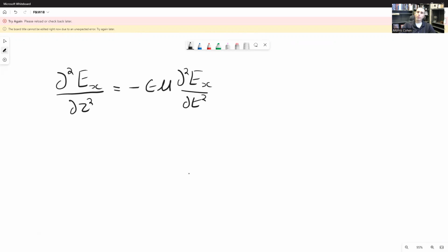All right, now, one thing that we had figured out earlier when we talked about phasors was that taking a time derivative, if we convert that into the phasor domain, is equivalent to multiplying by j omega. So here we've got a second time derivative, which means it's as if we're multiplying the phasor of E by j omega and then j omega again. So let's rewrite this in phasor form, and it's going to look like this.